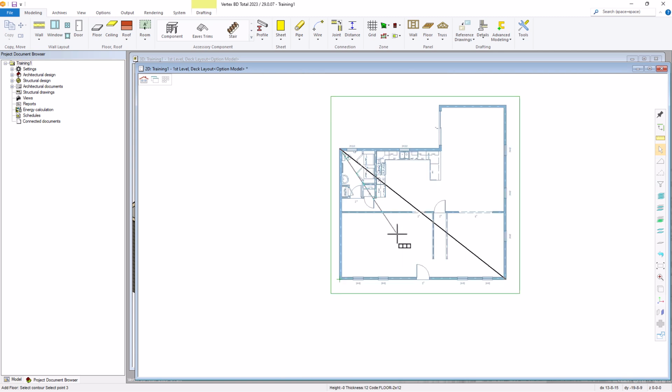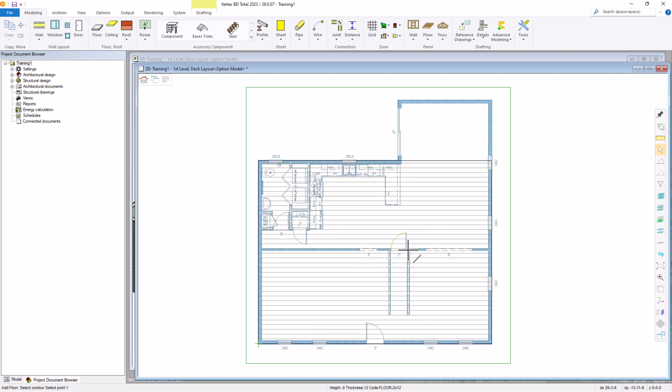And when I hit V to confirm, what's going to happen is it's going to expand based on these 2 point extents and create a rectangular shape. So if I hit V to verify, it took those 2 corners as the extents of this rectangle and created this shape. Now I can go in and I'm going to hit escape to get out of the command.